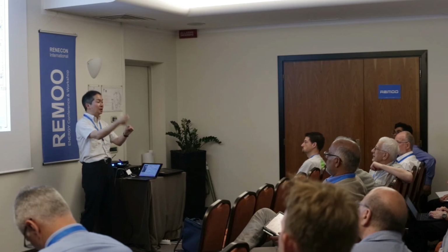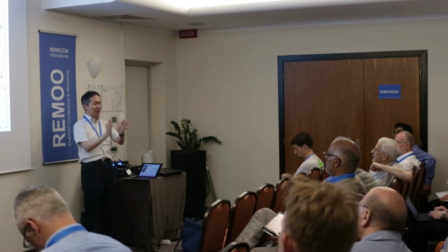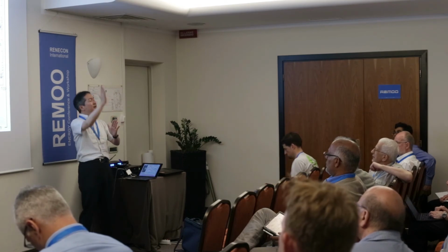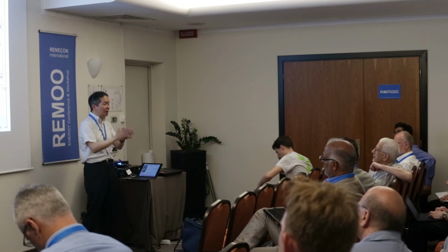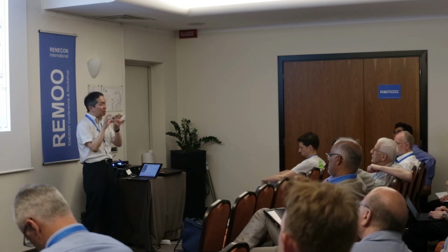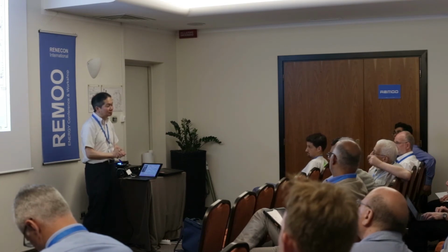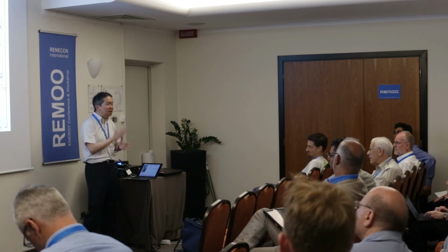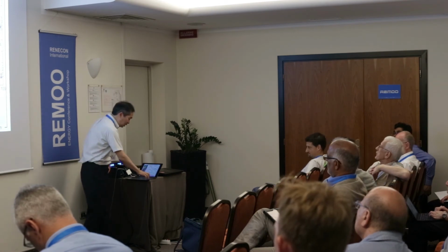Then we can evaluate the drag coefficient in the linear shear flow. It's slightly different from the standard cases, and by inputting all these measured data, you can easily evaluate the lift coefficient. No problem. But you have other forces. You have drag on the bubble. Yes, I already inserted the drag force and things like that.